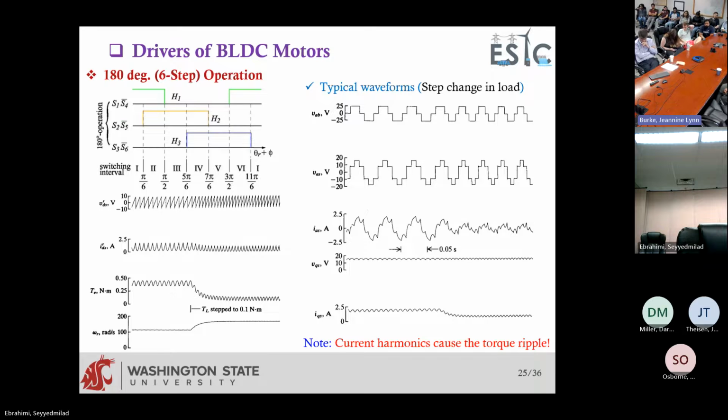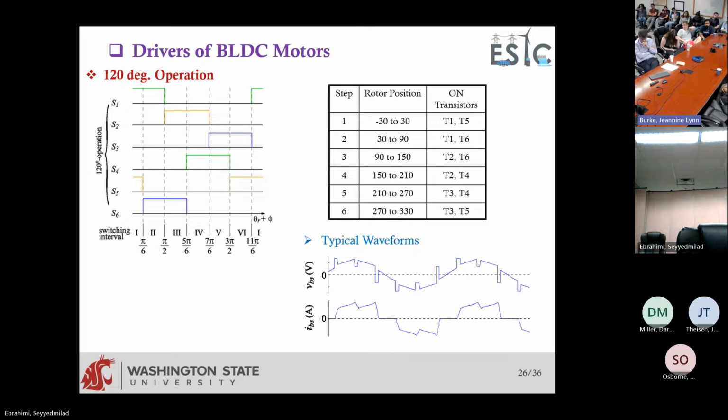The other one is because of this. This is when a phase turns off. So you see that this is the current of phase B, and phase B is 0. What has happened is, at this point, phase B goes out of the circuit, it is replaced with another phase, and it becomes 0 and it turns on here.